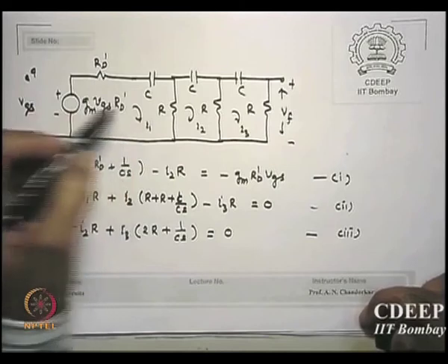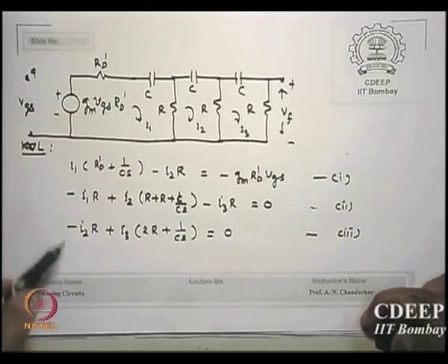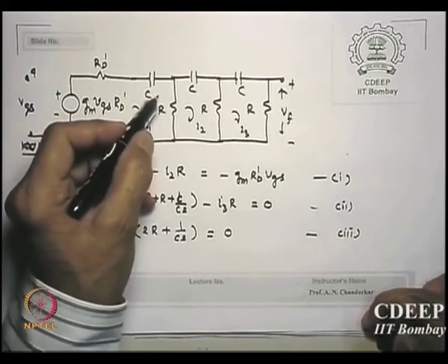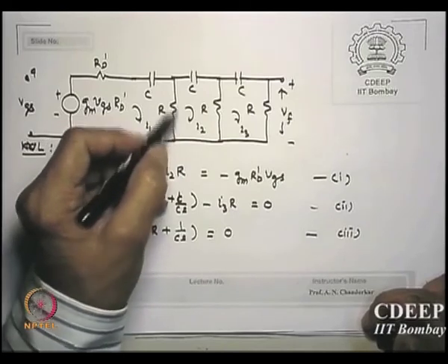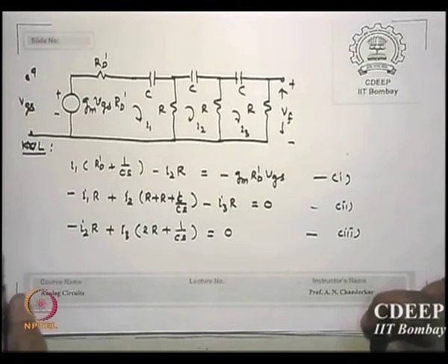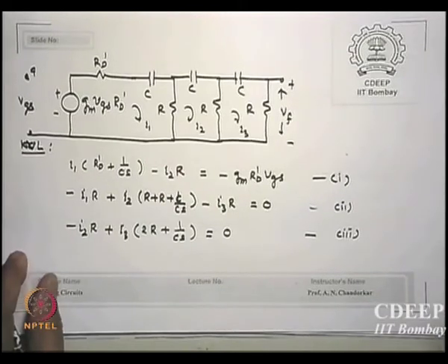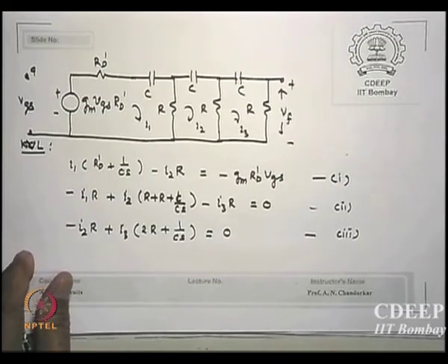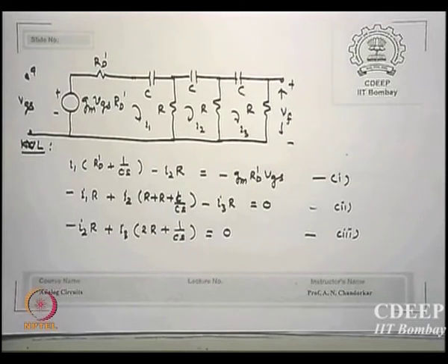Simple Kirchhoff's law, nothing very serious. This is KVL going to be done. At every loop currents are assumed. We write 3 equations. Please remember, I1 flows in this, but I2 flows in the opposite direction. That's why the signs. You have done this in your basic circuit courses, so there is nothing great about it. As I say, there is no RA, there is no source resistance there. Is that okay? So if I write these 3 equations, and you need not, because this is given in Sedra Smith, this is a trivial network.